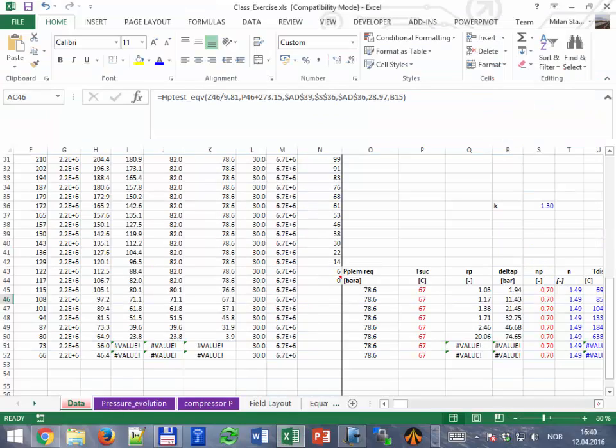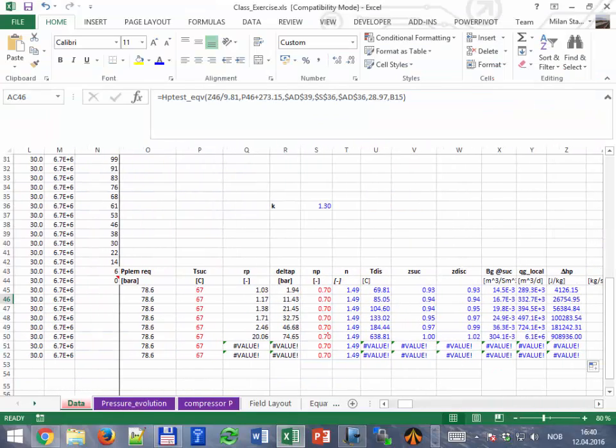Okay, so let's say now that we need cooling from this here. We could be bypassing the cooler, but this time we have to use cooling, okay? And the cooler, I told you, creates a delta T of 27. So at the end, this temperature will be 50 here, exactly.